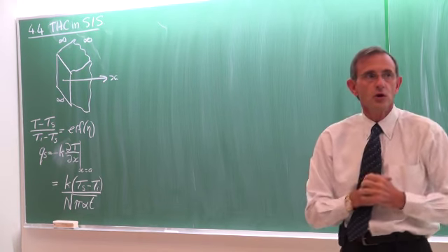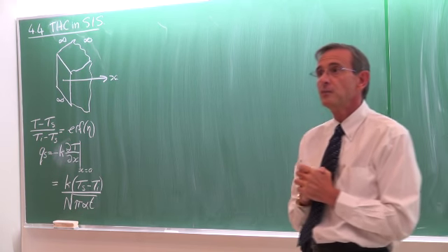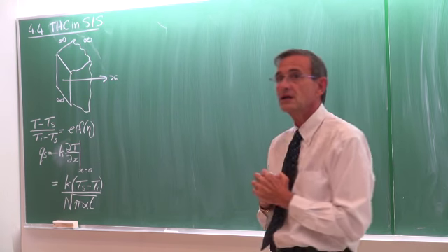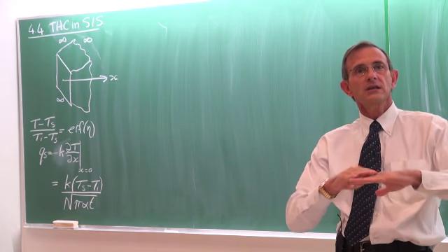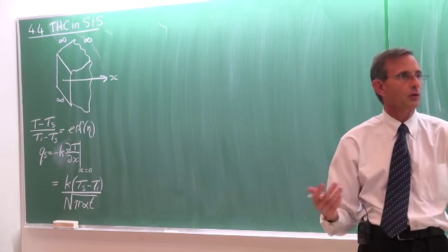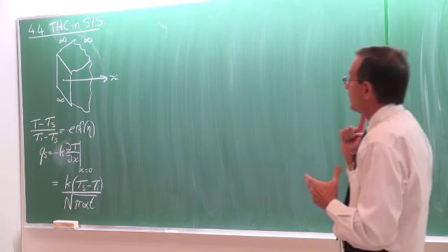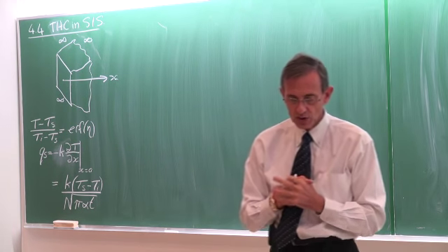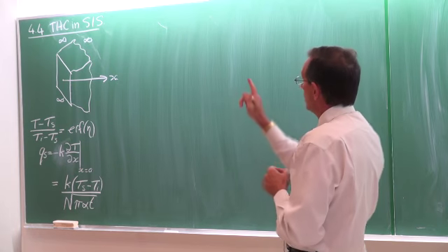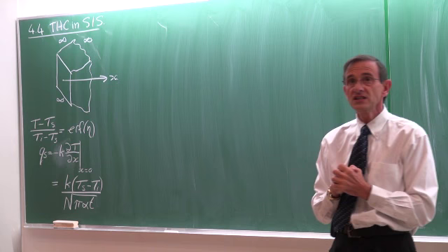The second part of the work was looking at conduction heat transfer through plane walls, cylinders, and spheres, but one-dimensional. There are equations to be solved. They can be very complicated, but you can also make them much more simple. Then we've started looking at transient heat conduction in semi-infinite solids.